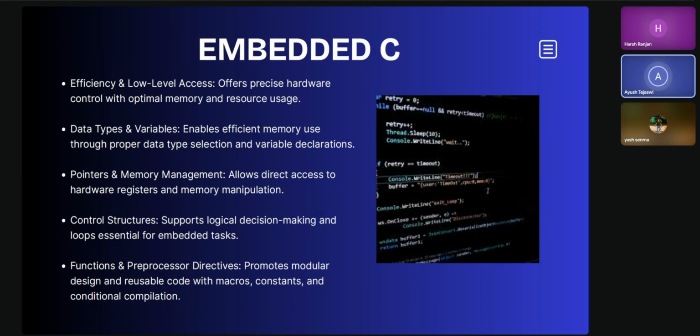We organized our code into header files for macros and port configuration, functions for wash, rinse, spin, and other functions, and interrupt handlers for external events like start and stop buttons. Using modular design, we ensured reusability, readability, and ease of debugging. This approach also mirrors real world firmware development.